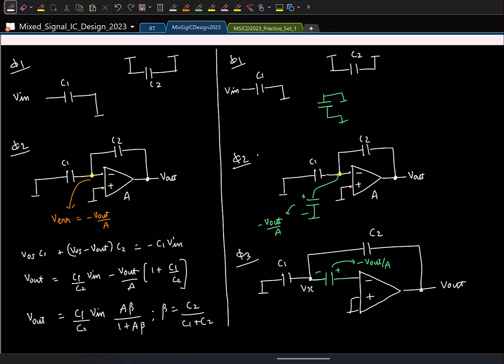Even the third clock as well as the second clock, everything must be non-overlapping. See, when I have this, C1 will get detached, right? That's okay, it can be detached. We are not disturbing the charge. We are not changing the V out. We'll then remove C2 also because that also has phi 2 in it. See, we want C2 to be connected like this in phi 2. We want C2 to be connected like this in phi 3. We have to hook up the circuit like that.